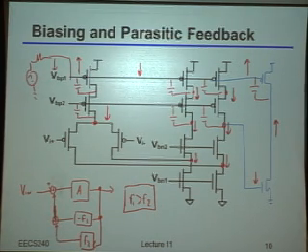What you're saying is actually a pretty good idea, but I just want to make sure we draw it the right way. Well, my first thought was if you just put a big capacitor. Oh, okay. So you wanted to put a big capacitor here. Actually that's not a bad idea. That's in fact a pretty good idea. Because notice what you're really doing by putting a big capacitor there is you're saying, well, even if it's positive feedback, as long as the gain was less than 1, maybe I don't actually care that much. So I'm just going to put a big, huge cap here to suppress any of those coupling effects. That's indeed a very good idea.